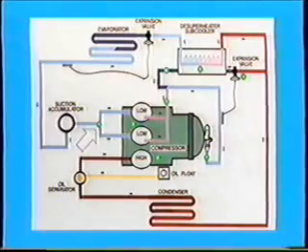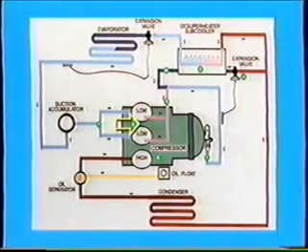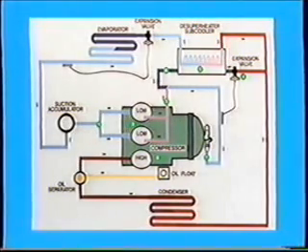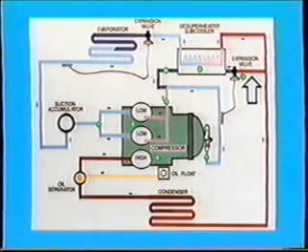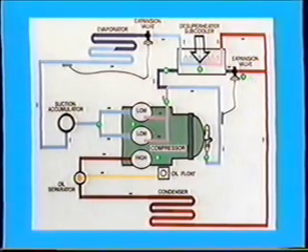On refrigeration, the two low-stage cylinder banks compress the refrigerant to an intermediate pressure. Refrigerant at the intermediate pressure flows to the intermediate manifold. A tap off the main liquid line directly expands the refrigerant at condensing pressure to an interstage pressure in the subcooler. Liquid on the way to the evaporator passes through the heat exchanger and is subcooled.